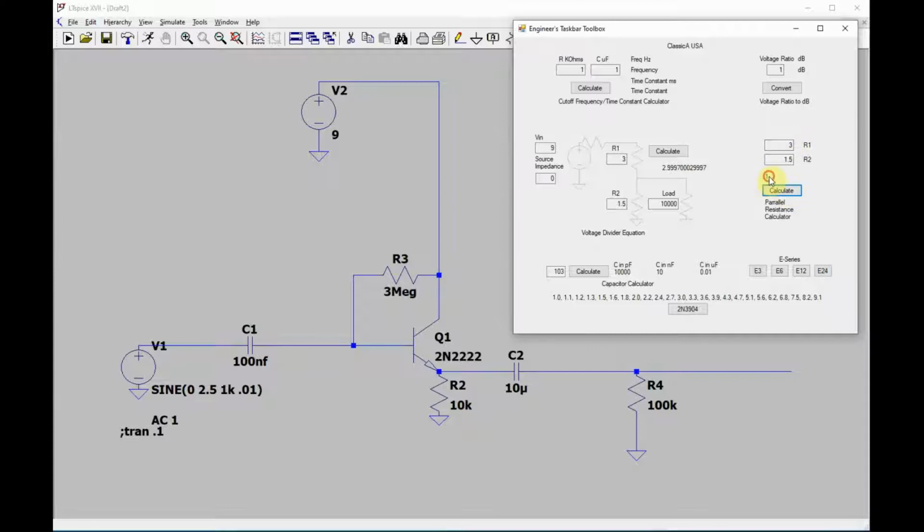Okay, it's calculating it to be 1, so that's 1 meg input resistance. Now if this is higher, it's 1.5. So if you have a very bad transistor, poor HFE, then this ends up dropping and you lose headroom. You also go from 1.5 meg input impedance down to 1. So it's totally dependent on the HFE.